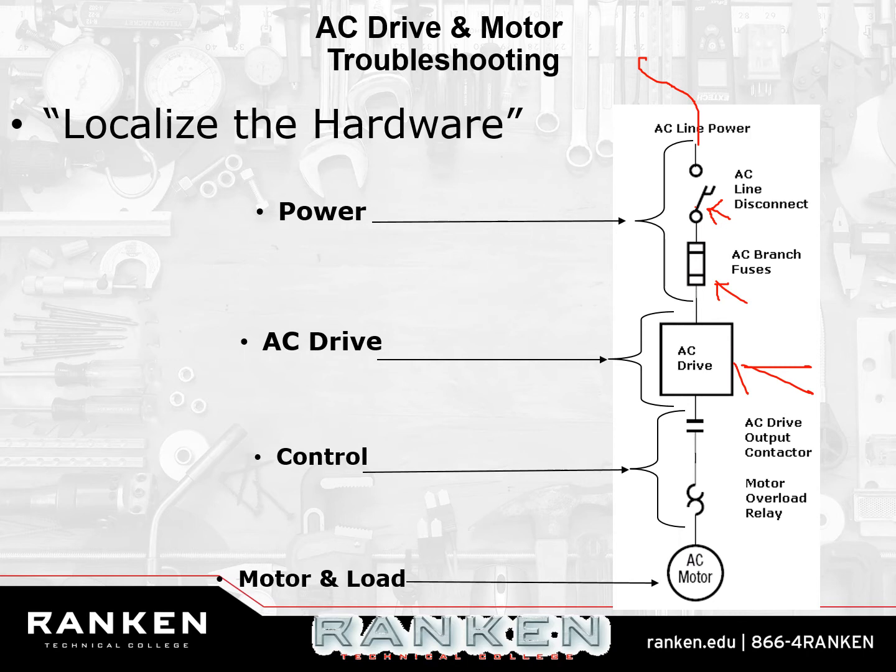But by the time you get down to this point of troubleshooting, you've already made sure that you have power going to the drive, you have good fuses, the drive is functioning as best as you can figure, and you've checked the codes that are coming out of it, and there's nothing major. Then you check the control. If all of this is working, that motor should turn on.